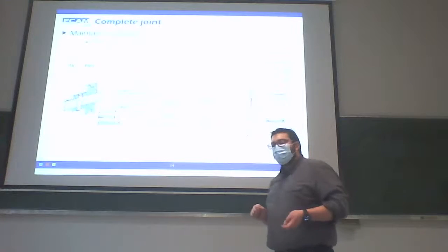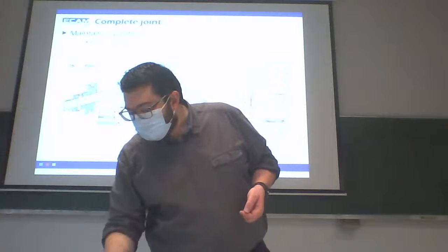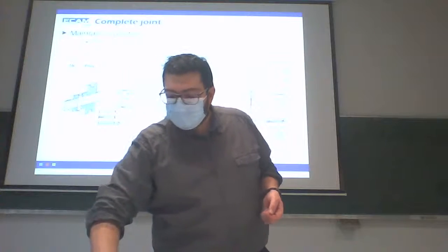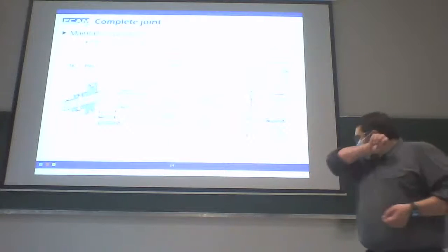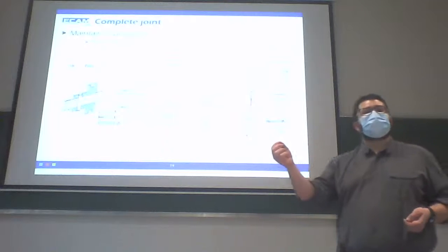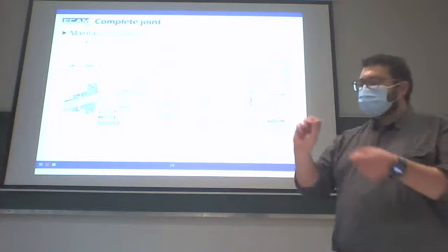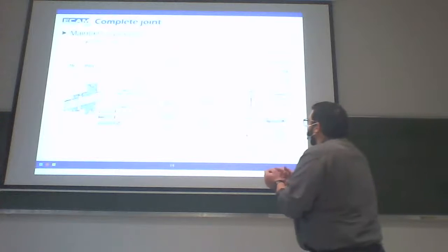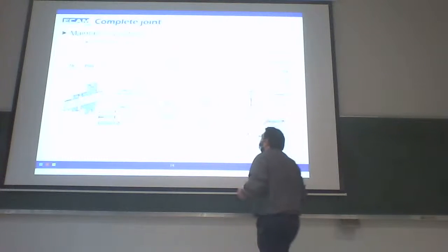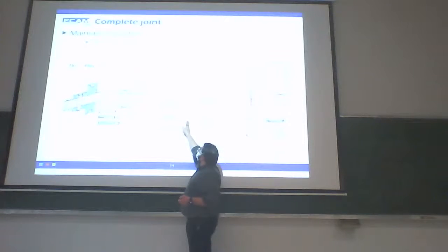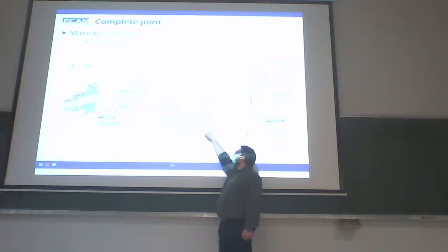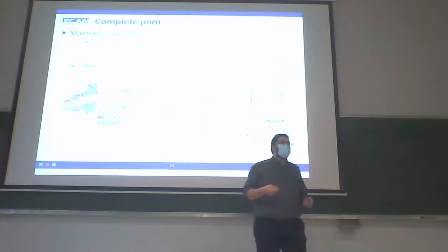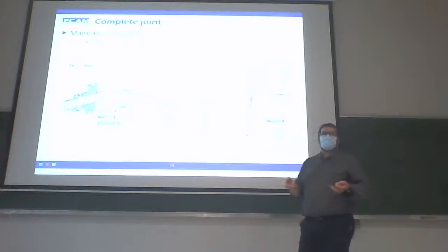In the middle, the split pin. Okay, you will use it. It's a pin like this. We'll use it during technical workshop in Fab Lab. Maybe some of you have already used it. Okay. It's a pin with two legs. We put the pin inside the hole, and after we'll fold on each side the two legs of the pin to avoid the movement of the pin. In general, the legs are too long, so we cut them.